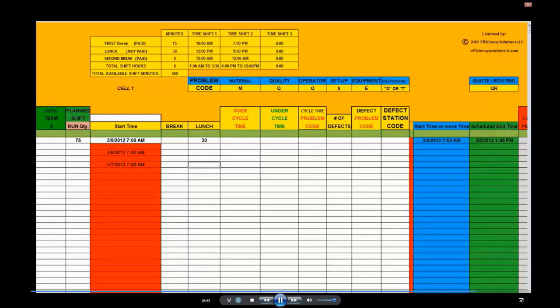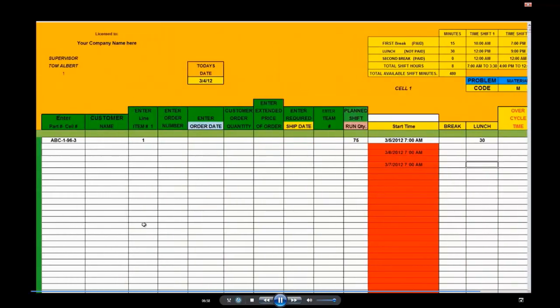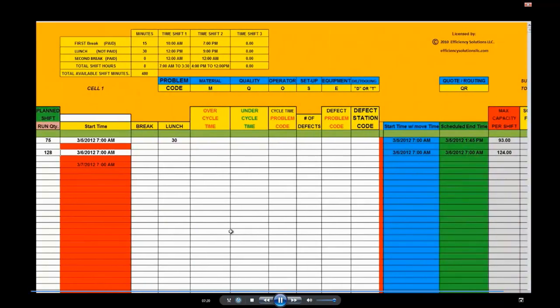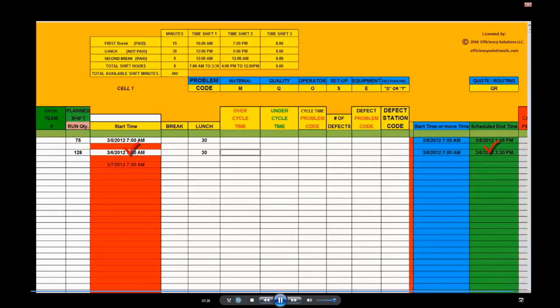As demand fluctuates, we schedule production according to demand using the real-time scheduling module you reviewed here and in earlier videos, and track efficiency to quotes and routings, problem codes, overproduction, and defects on every customer order that is produced in real time. The actual in-plant line balancing processes can be difficult and time-consuming, and for those reasons alone, you need to be relatively certain of what your results will be for the resources and time used in the design and improvement processes.